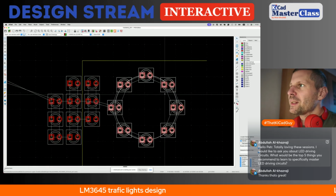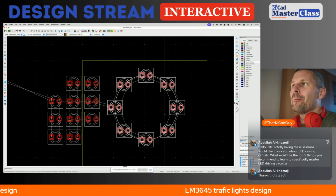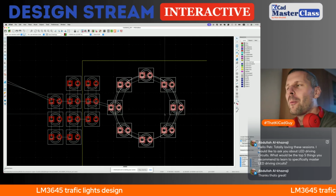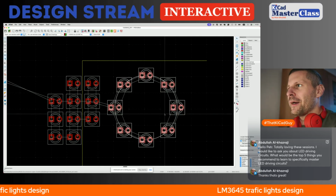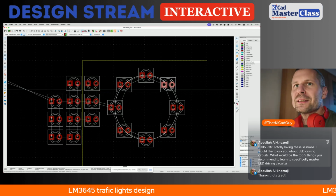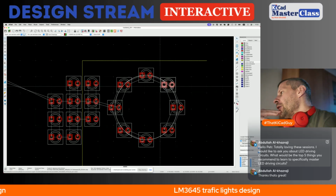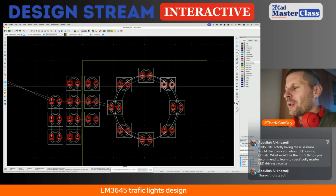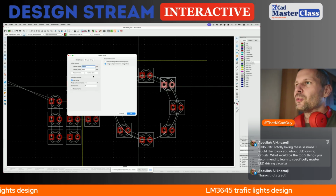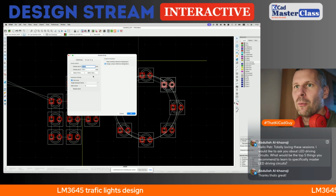Yeah, we evenly distributed LEDs along the perimeter of the circle. But as you can see, KiCad created new LEDs, it put new LEDs into the schematic. So my task will be to manually reassign numbers of these LEDs, because create from selection doesn't have the ability to rename or to keep the designators of the first component.